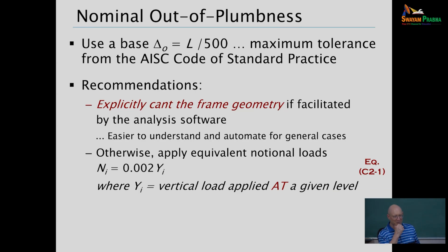You can figure it out and do it, but it's more direct to use your smarts to just say, oh, let me just lean the frame over. Now I've accomplished what I need for these effects by explicitly modeling that. Now, for ordinary rectangular frames, it's not that hard to use notional load, and many software providers prefer it. You might say, why?